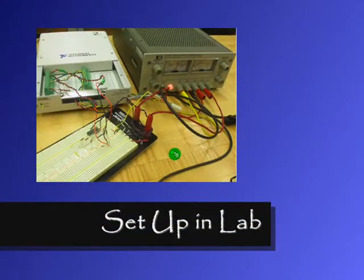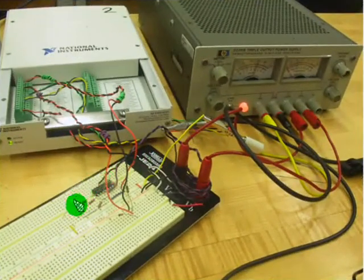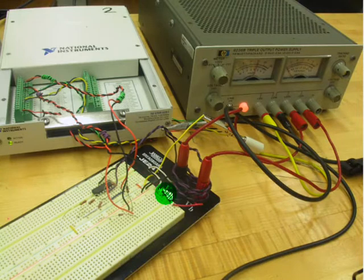Here's the setup we used in lab. Our breadboard shows our circuit that we built. The power is being supplied by the power source over here. We used 5 volts for our supply, and the op amp was being supplied by 15 volts. Over here you will see the DAC that we used to measure our voltages across 2 different resistors that we were able to then calculate our currents.